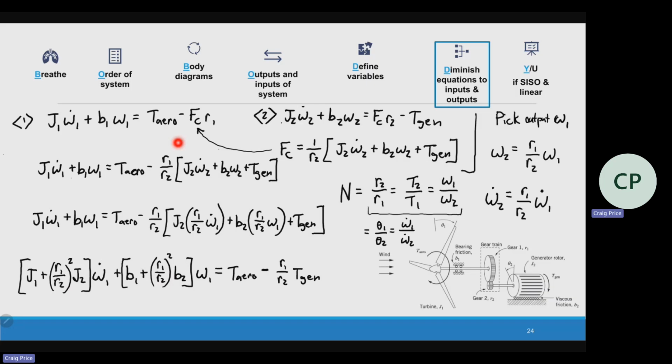We're looking at it in terms of speed. And now what we're left with is one first order system. So the gear allows us to simplify the system, to take something that's really complicated because there's the contact force in between. It's equal and opposite because the speeds are related. We can take this large system and create this one overarching equation that can model the motion.